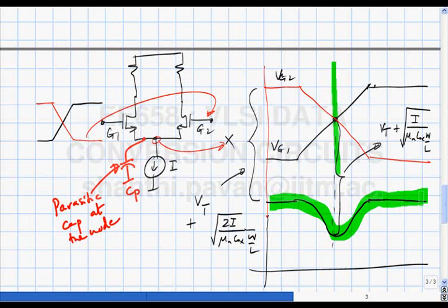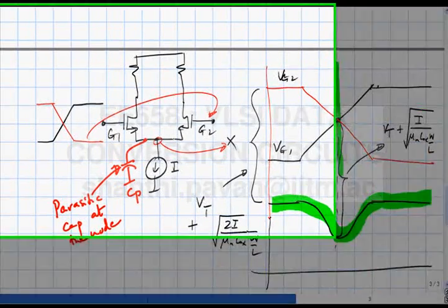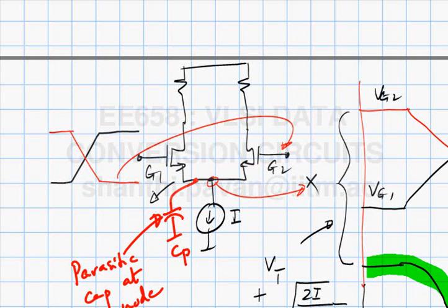If there is something like this, what do you think will happen to the current? What is the extra current being injected into this node? If the control waveforms are doing this, then the source-coupled node is basically doing that, which means the displacement current flowing through the capacitor is nothing but Cp dV/dt, correct?